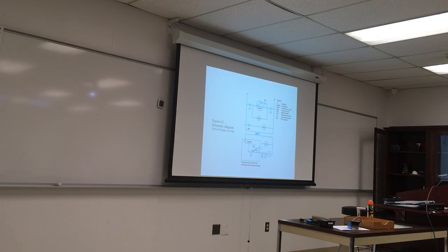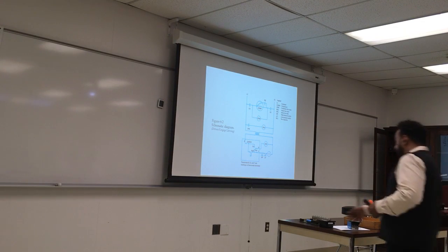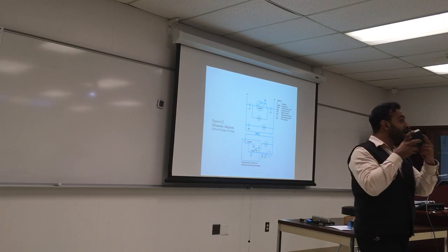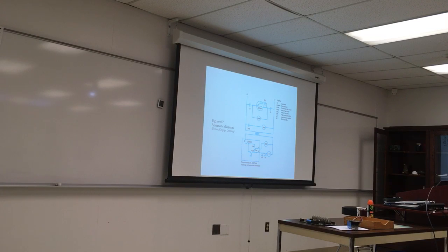And what do you do if there are no schematics? Thank God there are a lot of schematics everywhere now. Well, you can call the company and they'll send you a print, but that's really annoying and takes time. Now you just Google, for example, the model number: Honeywell primary control R7184. I'll get the entire manual as a PDF. And it's good to have them printed out ready for you.